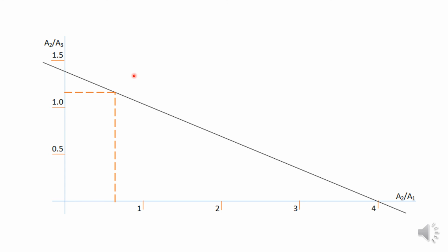And once you do this, you know the forces basically. Once you know these ratios, you can look up your tables of cross-sectional areas of standard steel sections, and obtain sections in these ratios, and you can design using this.